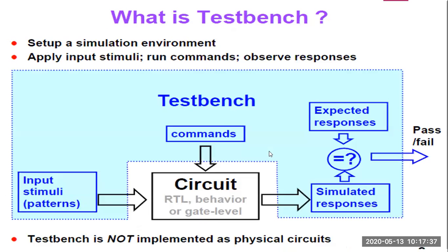So when we come to the concept of a test bench, what is a test bench? A test bench sets up a simulation environment, applies input stimuli, runs commands, and observes responses. So the basic thing is that it collects a set of input patterns sent to the circuit-level operation, that is, behavioral level, gate level, or RTL level circuit simulation.